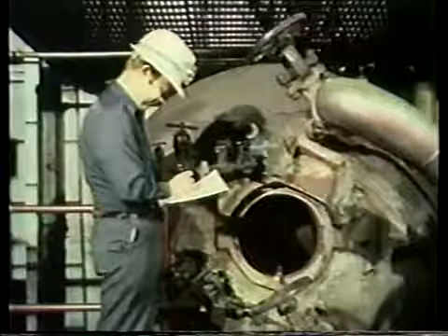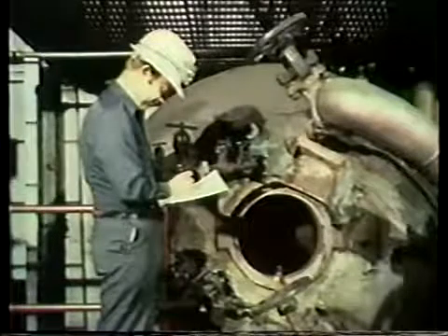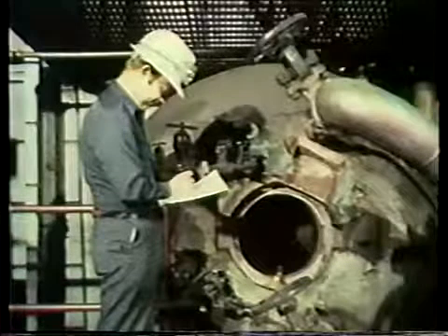In some plants, in order to keep track of the tools, the observer outside the vessel takes an inventory to account for everything and everyone going in and out of the boiler. Another way to make sure no tools are left inside is to tie them to yourself. This also prevents tools from being accidentally dropped down a tube or downcomer, where they'd be very hard to get back.